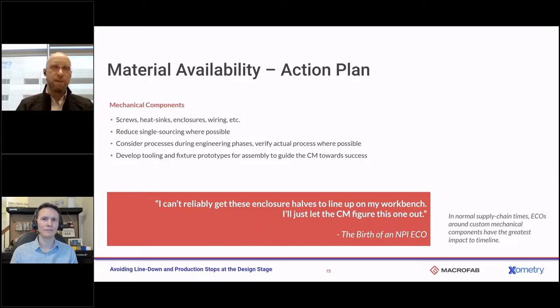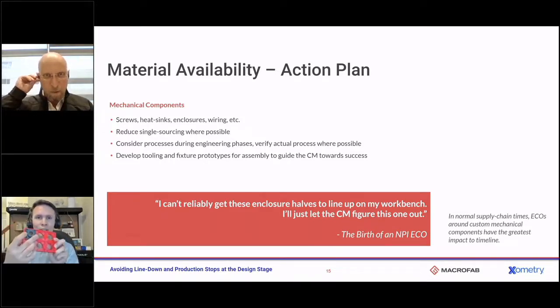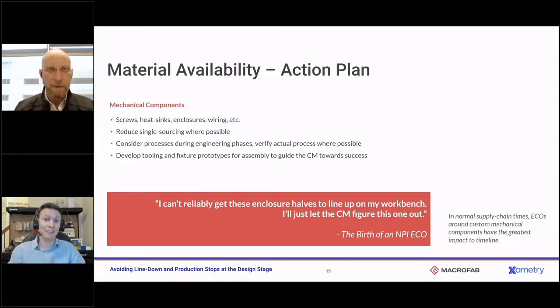Keep testing each part of that process as you make design changes, just so you can be fairly confident that there aren't going to be any major issues as you get into it. Yeah, absolutely. And by the way, fixtures can be as simple as a nice little grid block or something like that. But this is where additive manufacturing really plays a huge role. A lot of these checks and fixtures, at least for the mechanical components, assembly enablement tools, additive is just awesome for this type of work. We even have ESD materials that you can 3D print.